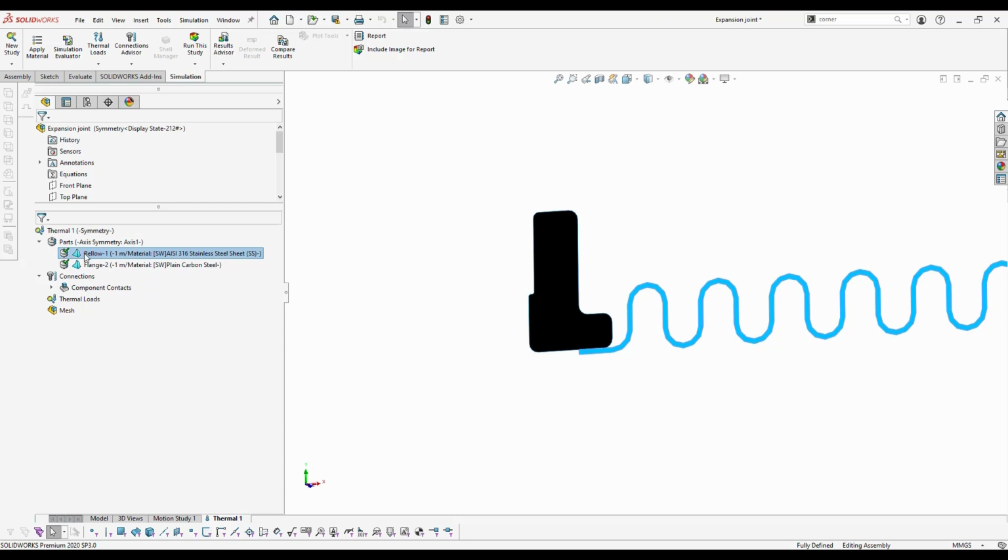This triangle here to the left of each of the file names, that's the symbol for a solid mesh. Now, I'm going to get to some tips and tricks a little bit later, but there's three different types of elements. We have solids, beams, and shells. So that triangle is telling me I have solid elements.